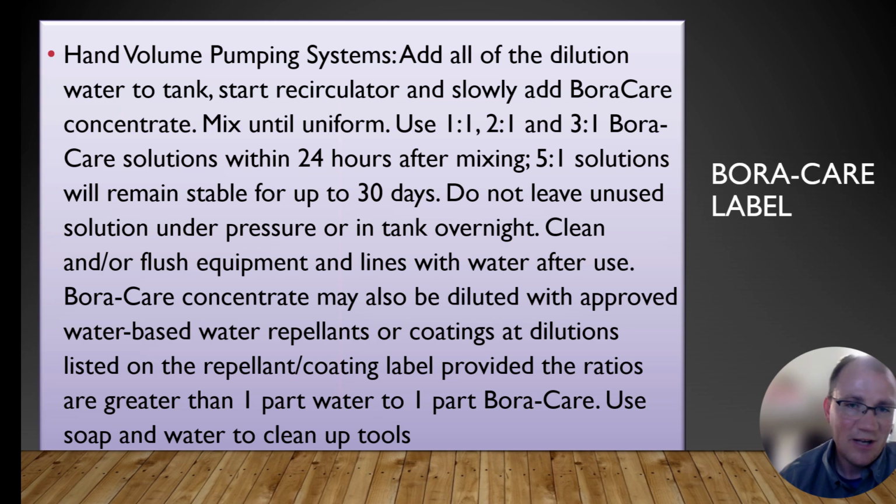I definitely wouldn't suggest leaving this product in a tank for 30 days. This product likes to crystallize. I found that out. Even when it talks about cleaning and or flushing the equipment in lines with water after each use, that's hugely important. There's no worse product to crystallize and gum up your equipment than Boracare. If any of you have ever used it, you probably know exactly what I'm talking about. So my suggestion is mix exactly what you need to use, and then make sure you run at least a gallon of water through your equipment to kind of knock that Boracare out. Because once it crystallizes in your lines, it's very hard to fix your equipment up after that.